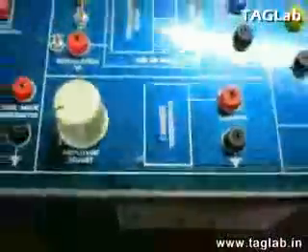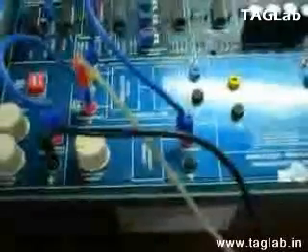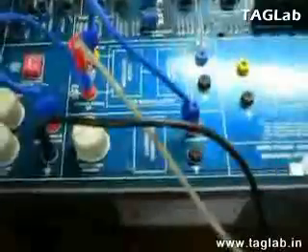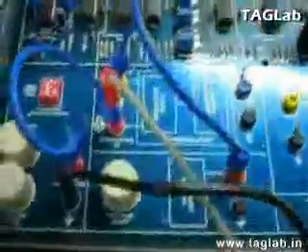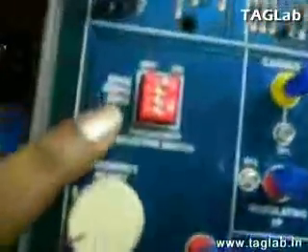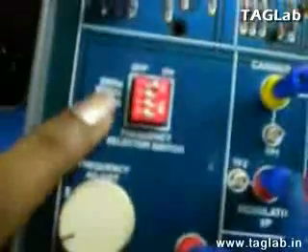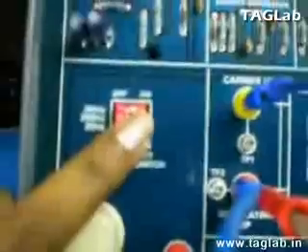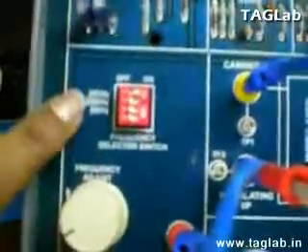Now let's observe the amplitude modulation wave. Now here we have selected the 2 kHz frequency, and you could see the switch is in on position where 2 kHz has been selected. The sine wave generator 2 kHz frequency is given to the modulating input, and from the carrier generator the output has been given to the carrier input of the modulator block.